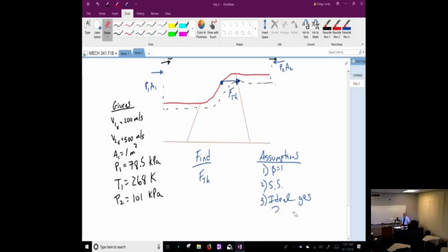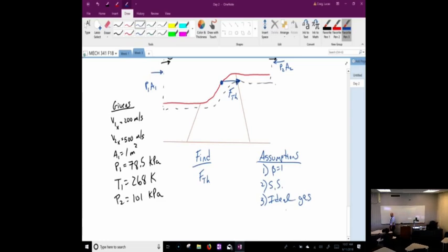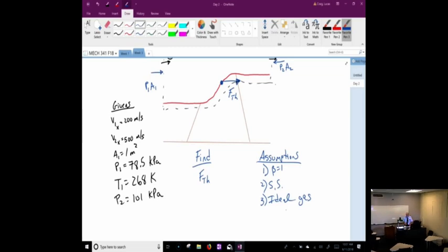You remember the compressibility factor, if it was not ideal? P equals rho RT, but you had to include the Z on the right. That chart's in the back too. Got it, you're good there.